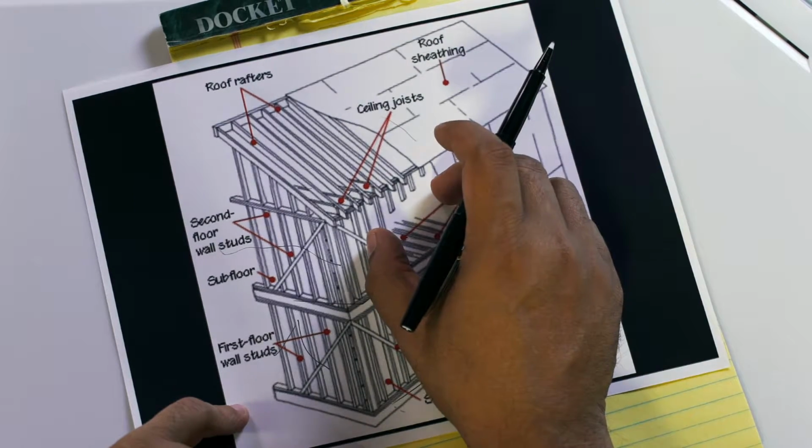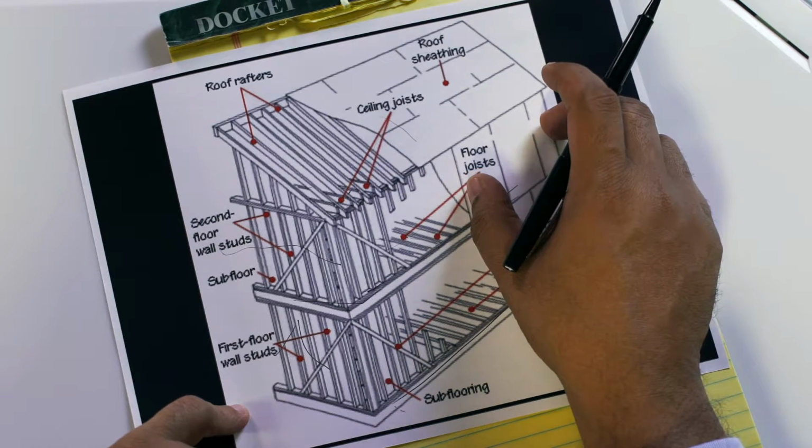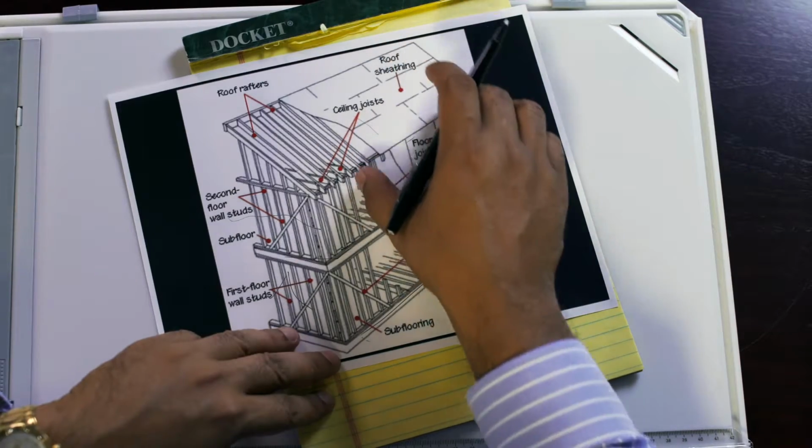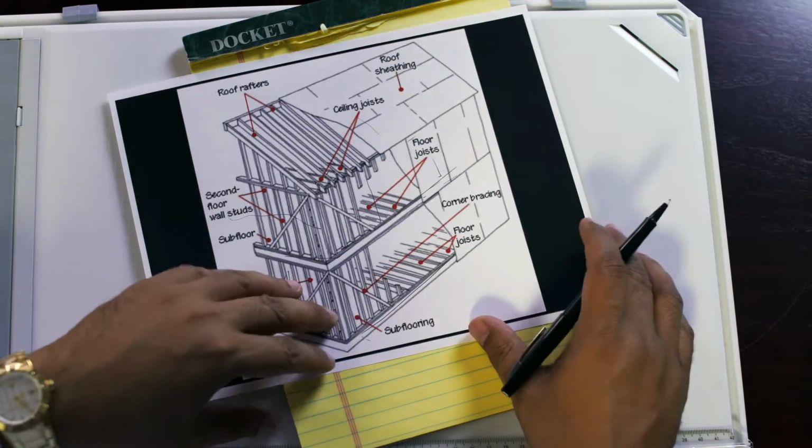If we remove areas of wall, then we have to substitute that with columns. If we create large openings here, we have to substitute that with columns so that we have continuous load path. I know that when architects design buildings, they always like to have large open floor plans. So do I. But let me give you an example.